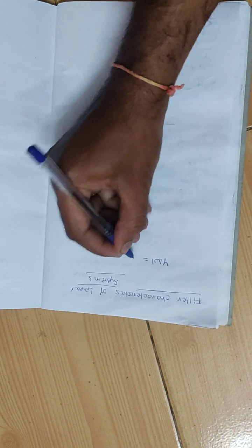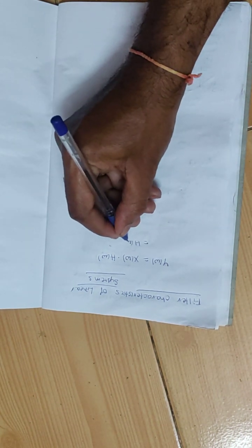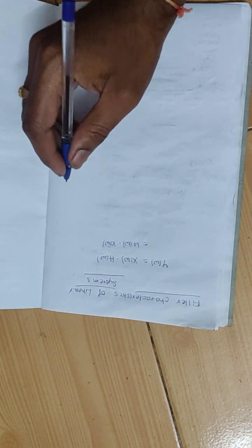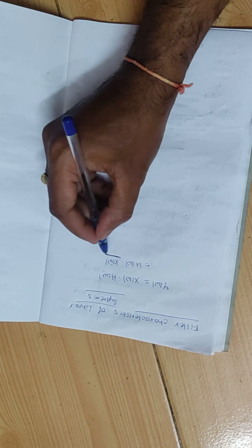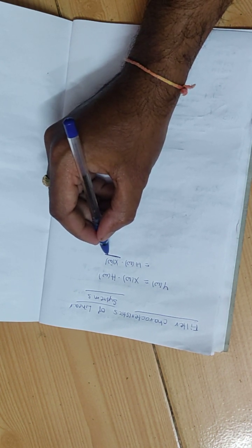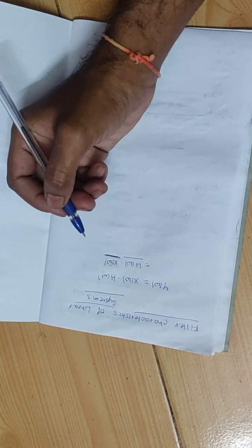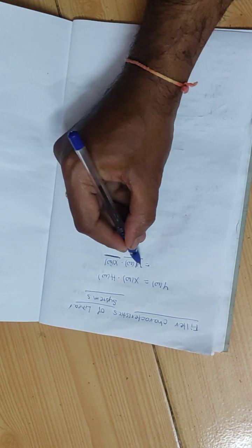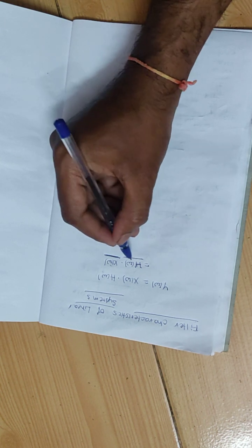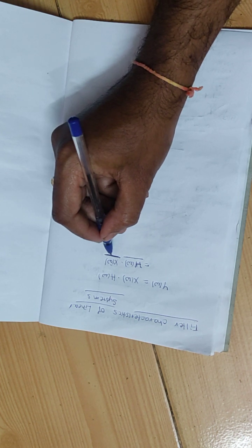Y of omega is equal to X of omega multiplied with H of omega, or H of omega multiplied with X of omega. So, both are the same, and if you carefully observe, the spectral density function of X of omega is modified by the H of omega. So, that means in some way this transfer function is changing the spectral density function of X of omega.